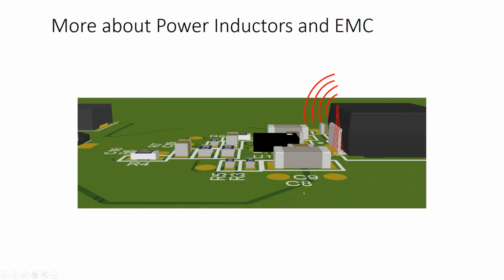So how does that look in terms of a board? This is just a 3D representation, right? We've got an inductor with this metal clip up here, and it will act as an antenna and could potentially radiate and be picked up by other areas. And if this energy bypasses the return path, which would be first to this capacitor here and then back, this is going to end up showing up in our radiated emissions plots.